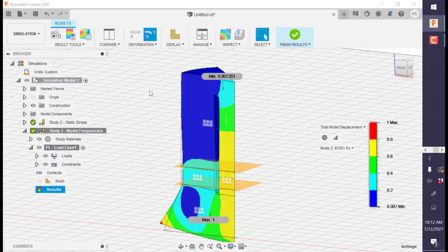Modal analysis solves for the natural frequencies of resonance that are permissible in this structure. Now, because of the way I set this up, we won't have any torsional modes, and there will be a limited amount of bending modes. But the longitudinal modes, where the ends are extending mostly linearly along the axis, are what we're actually interested in for this specific transducer.